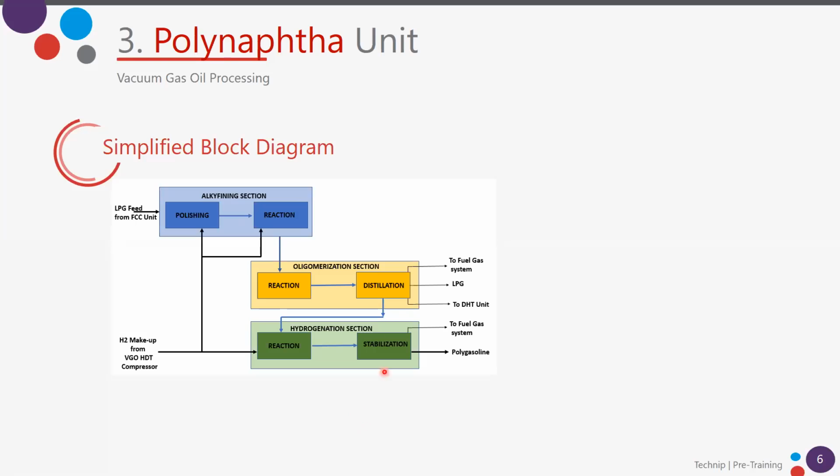Yeah, remember that also you have here a high quantity of olefins, but smaller olefins. What you are going to do is to create bigger olefins in the reactions. So anyway, can you use these olefins directly in the gasoline pool? No, because you have high olefin content. Because the idea is to create higher olefins, dimers, trimers in this reaction, okay?